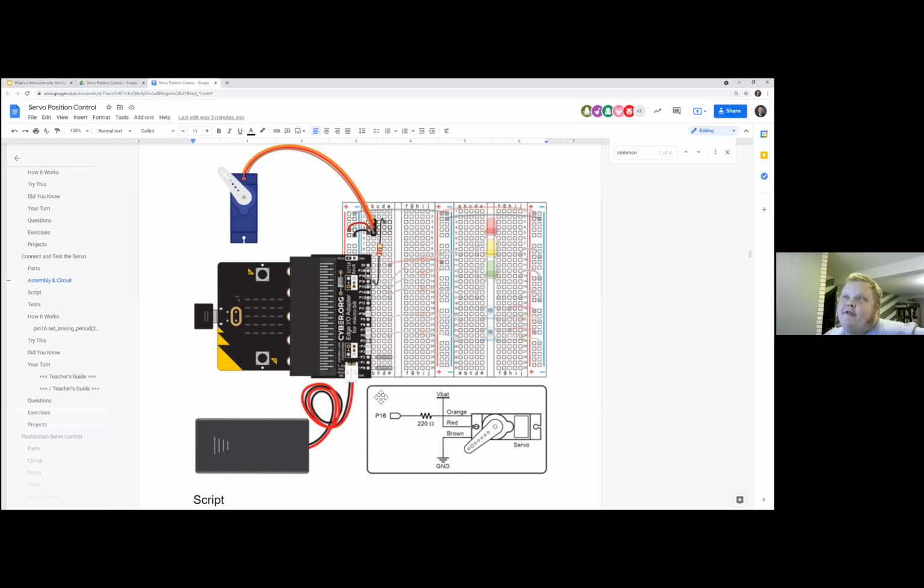I've had a couple of microbits with this connector break, and so with the kits, we actually cut the red wire and then put in just a toggle switch and taught the kids soldering for that. So they did a small soldering connection, and that way they could stay connected in the little Harbor Freight tote kit, whatever we buy to hold it up, and then it reduces the wear and tear on it a lot. Right. But yeah, that's a cool thinking activity.